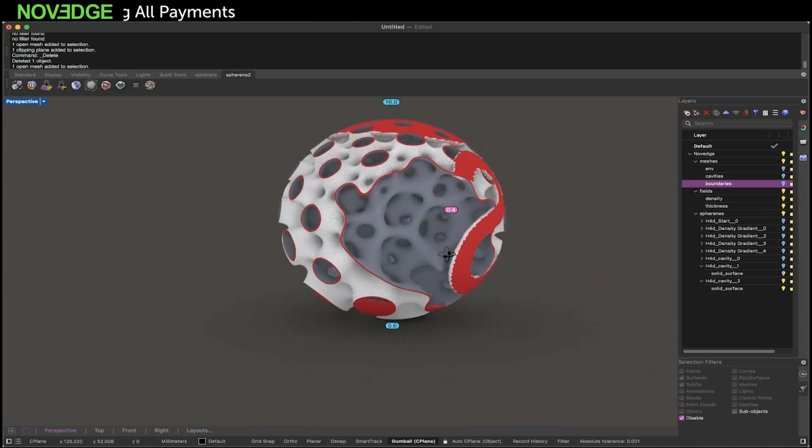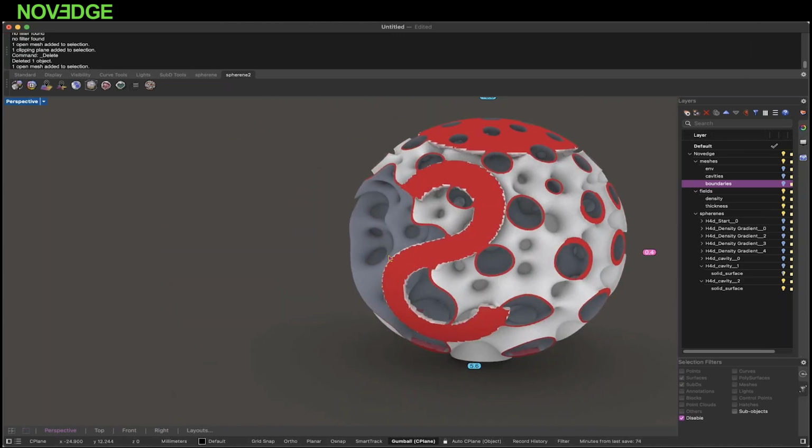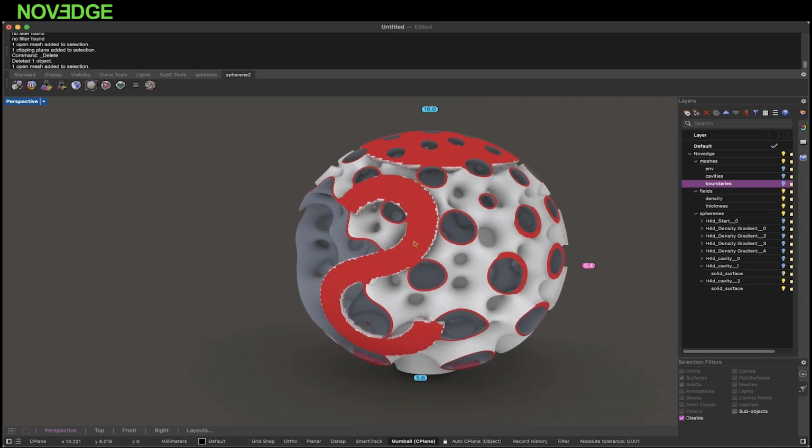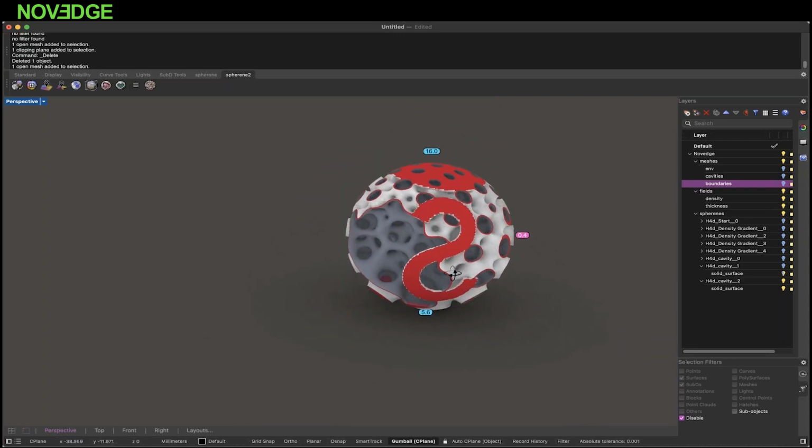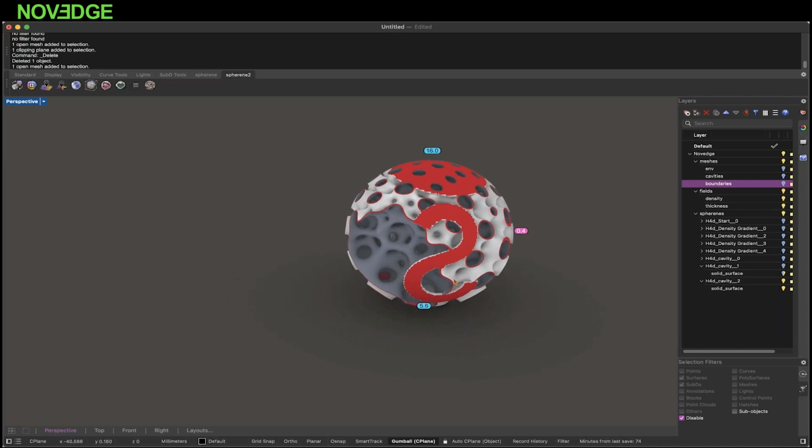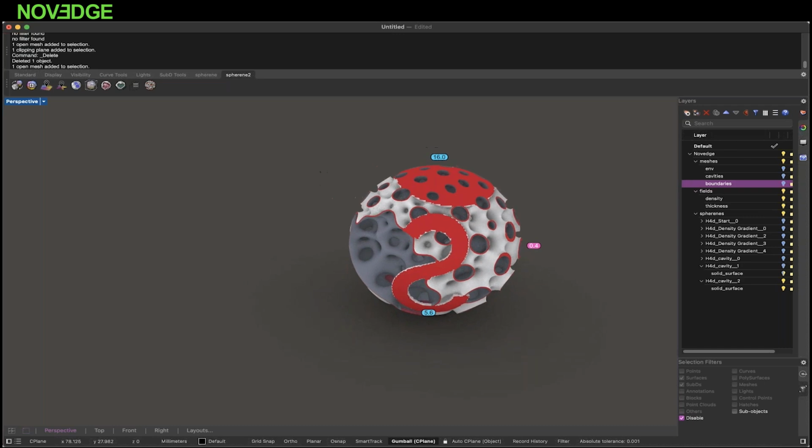So we have a super complex object made in minutes. So that's a really, really cool thing. I'm super happy that everything works until now. Let's go even crazier. We have a new concept called detail geometry. Think of it as a Boolean modifier, so you can add or subtract a geometry. But you can also say, as we did with the boundaries, should the Spherene thicken up to that surface or not, or what should happen there?